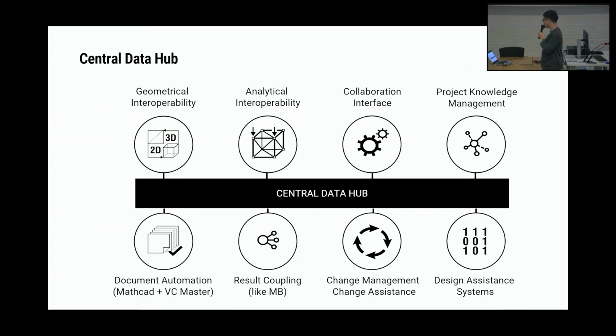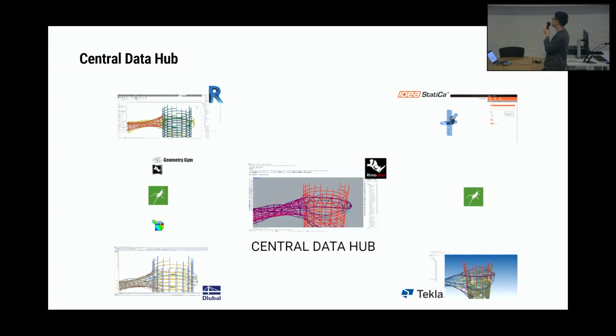And so the idea is that for this one project, we try to set up what we call a central data hub, where Rhino is the main source of information, or single source of information, where you have the structural information as an analysis model, but also the geometric information. It has information about where each component might go in terms of its relationship to each other. This then gets fed into the structural model, the BIM model, fabrication model, and a Tekla steel workshop planning model too. And as I mentioned here, basically using different tools, we can extract the data or the geometry from Rhino into all these other software environments so that we can actually have the same information but use other software environments to do the specific part of the project that is needed for that process.